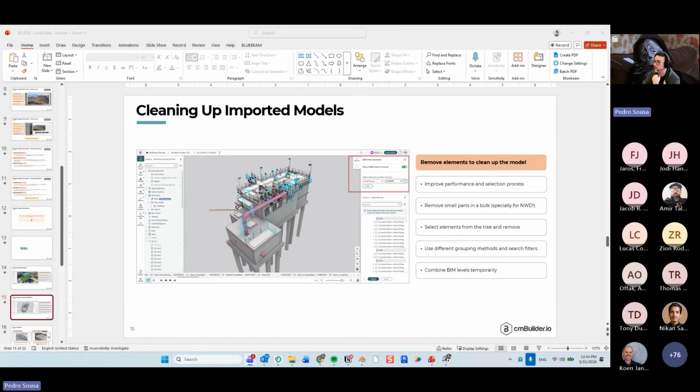So in terms of loading faster, we always suggest that you use Revit and IFC files because they have that tree structure, and also repeated geometries will be processed faster compared to NWD, NWC, and FBX files where every individual geometry is rendered as a single object, right? So there's no instancing in FBX and Navisworks files where that happens with Revit and IFC, which will guarantee a better performance for you to work with.